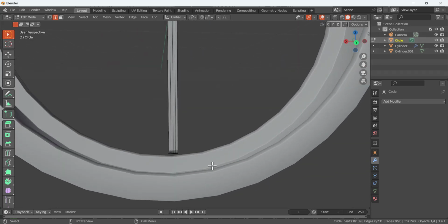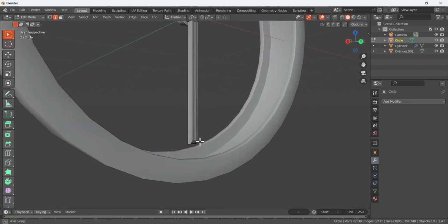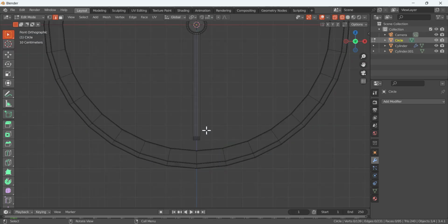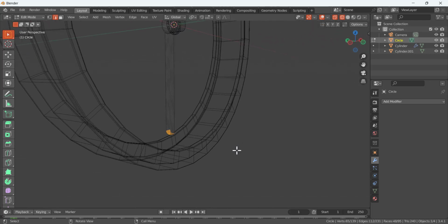Now for the hollow clock, this one clock needle is basically attached with this ring which is attached with the gear. So press 1 and shift Z, so you are in the wireframe mode. So you can select all of the vertices, then box select, left click to select and select all of these vertices.